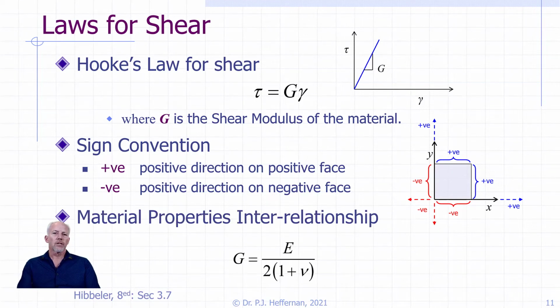And one thing to note is that the shear modulus, which we just looked at, is defined by Young's modulus and Poisson's ratio, nu. The three of them are all interrelated. So if you know any two of them, you know the other property as well. They're all completely related. Often a problem might give you just Young's modulus E and your Poisson's ratio, and you would then be expected to understand that you have been tacitly given the shear modulus. You just have to take a step to calculate it.